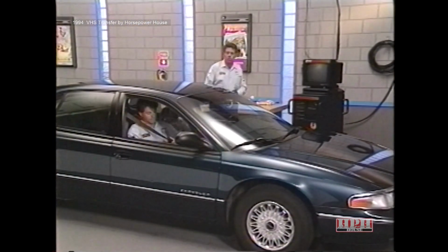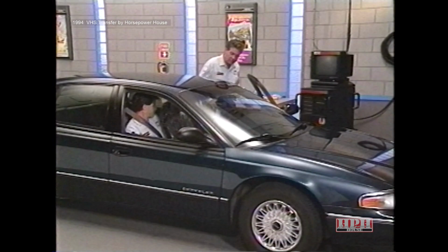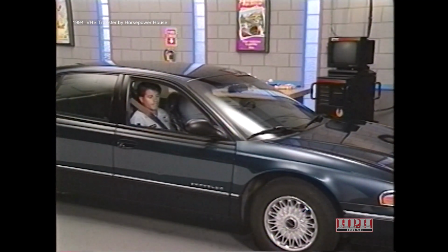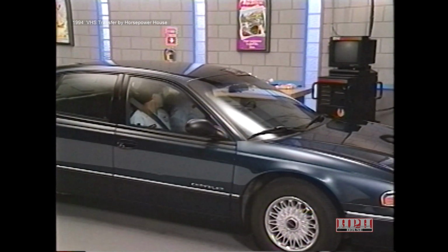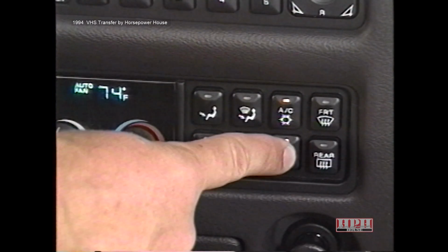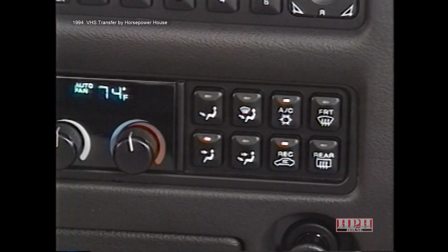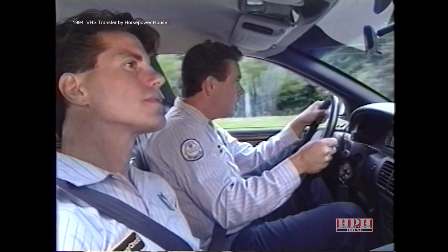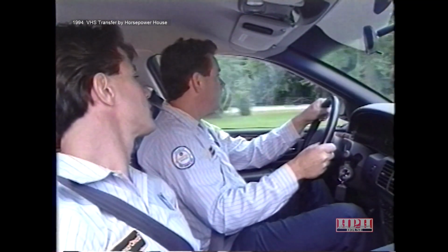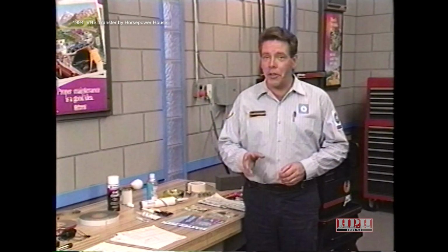If you're still trying to track down the problem area, begin by driving the vehicle at the speed indicated on the customer feedback form, with both the doors and windows closed, the heater blower off, and fresh air inlet doors closed. Listen for the noise and try to determine if it is coming from the inside or outside of the vehicle. You may need to drive the vehicle in the opposite direction on the test road, since a change in wind direction will sometimes vary or stop the noise.